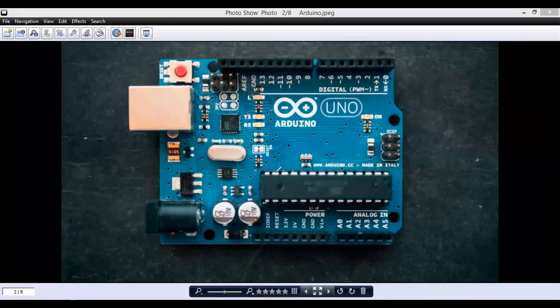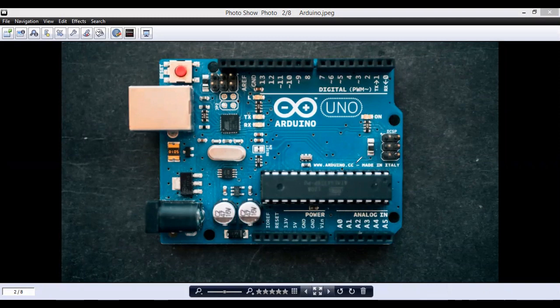So now we are going to be looking at the different parts of the Arduino Uno. As I told you, there is a huge bulky processor on the board, and in the SMD edition, it's actually smaller. So here is this big processor which I have circled. You can see it's huge. It's called the ATmega 328. In older versions of the board, it's called the ATmega 168.